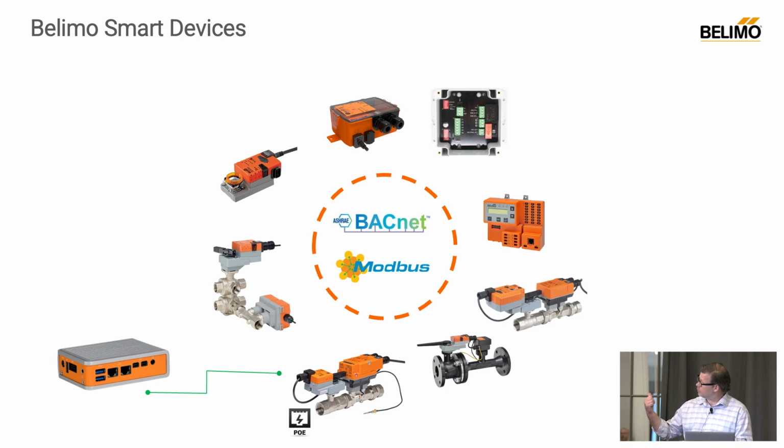Next one over is fairly new, the FSKN. This is a remote fire smoke damper testing. So NFPA, I think it was 2 years ago, now allows you to remotely test fire smoke damper actuators. So you send BACnet, discover, bring in the objects. There's actually one object, command, you send a test. It goes through its paces, opens and closes, hits the various contacts, comes back and gives you a yay or nay. So no longer do you need to do line of sight testing. So it's a pretty neat device.